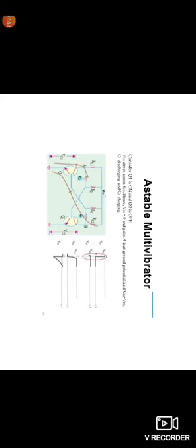In the second case, VCC is applied, so that through RL the capacitor C2 is charging. Point A of C1 is the ground point, and VC2 is equal to VCC. C1 is discharging and C2 is charging. Here, in the two cases, whenever Q1 is on, Q2 is off. Here Q2 is off, which means it is an open circuit.